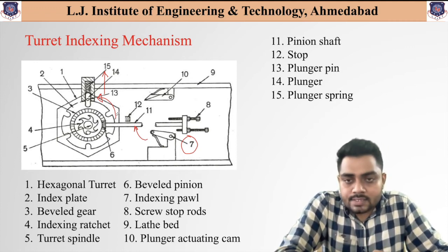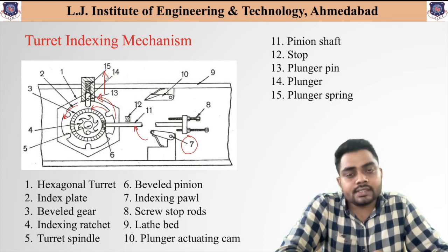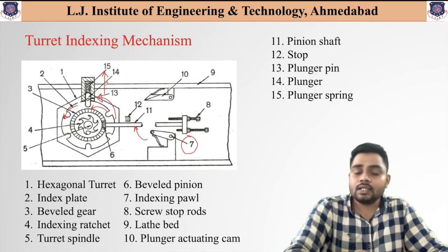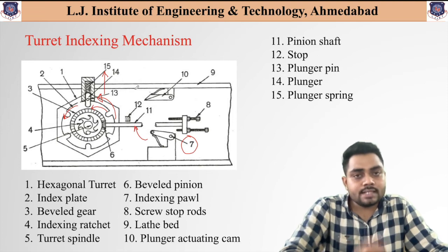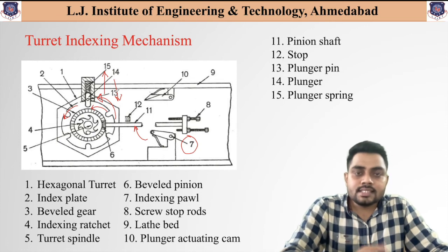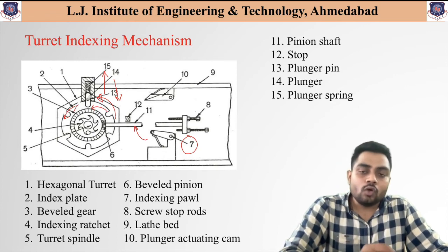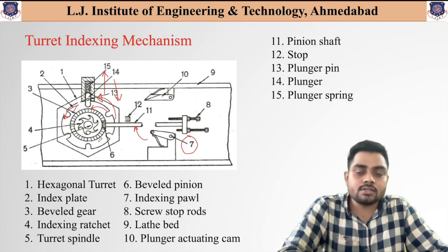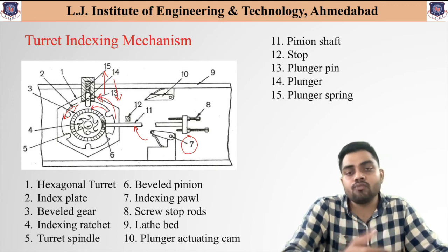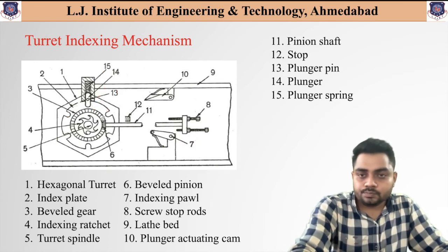So as this plate starts rotating, when it moves in the forward direction and these slots come over here, again due to the cam and follower operation that you will study in the subject, the cam operates accordingly and this plunger moves back in the downward direction. As this plunger moves back in the downward direction, the tool automatically gets rotated by one slot. All the tools are attached in these different slots which are connected in the outer or upper section of the lathe machine. So again, let me explain to you.